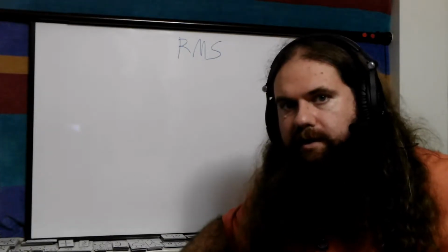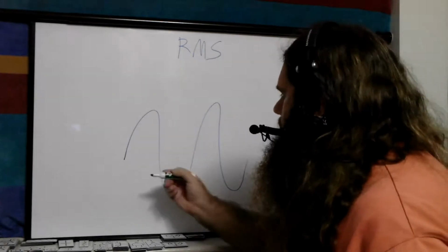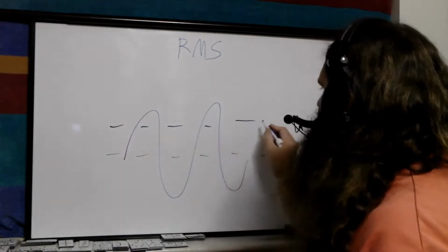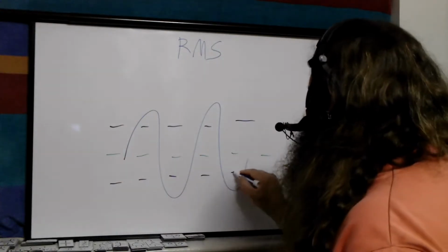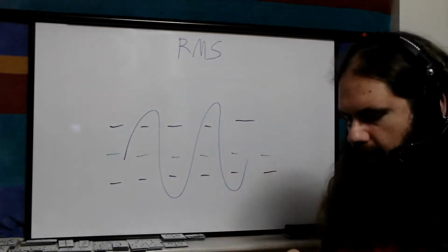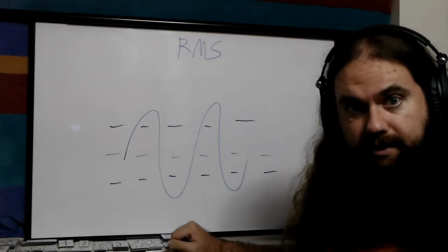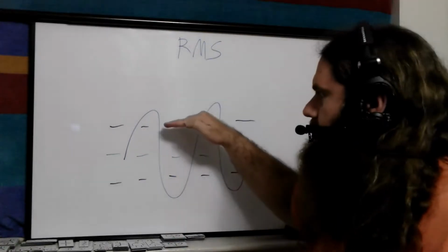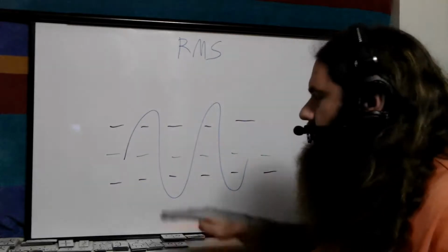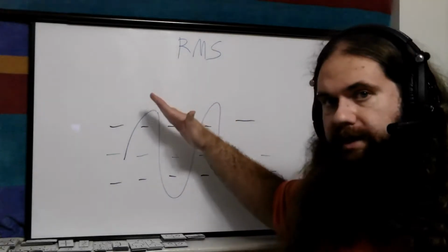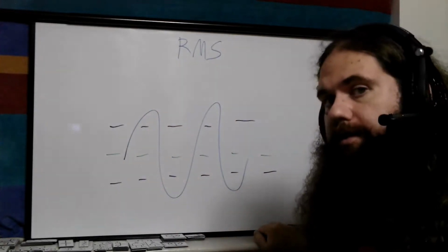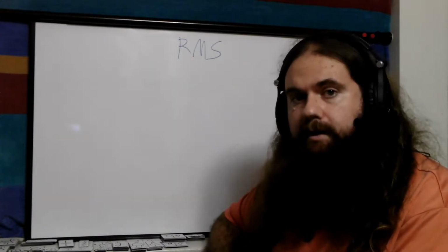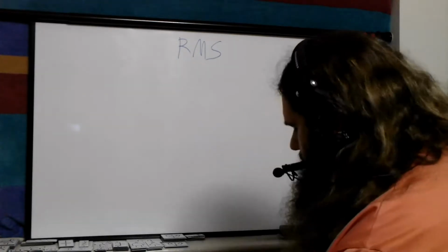When we say 120 volt AC, here's your AC, and if this is 0, then positive 120 will be there-ish, negative 120 will be about there, and the peaks go much higher and lower. Another reason why it said 200 volts AC on my meter for measuring 120. Root mean square kind of gives you a number that represents the waveform that's lower than its peaks and higher than 0, and always positive. So if you took the average of absolute values of samples, you would get a number that's useful, just less useful.